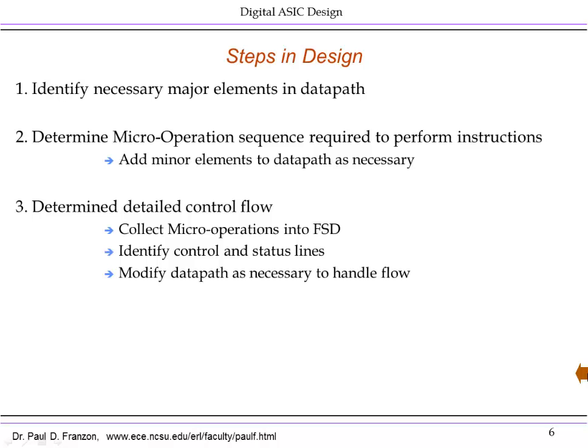But in general, in any hardware design, you can go from the algorithmic intent to a set of steps that have to happen in the hardware. These steps are best fleshed out as micro-operations. Key in a micro-operation is that it specifies a register-to-register transfer without getting into formal language. And then we'll go on to the detailed control flow in the next submodule.